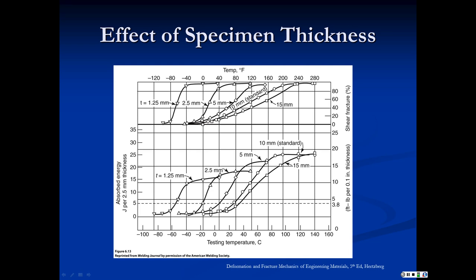Okay, so be aware that your specimens, now this is 15 millimeters, so that's still your Charpy specimen. Not much larger than your Charpy specimen dimensions. You're talking usually 10 millimeters for the Charpys. But obviously still not out of the woods here in terms of thickness.